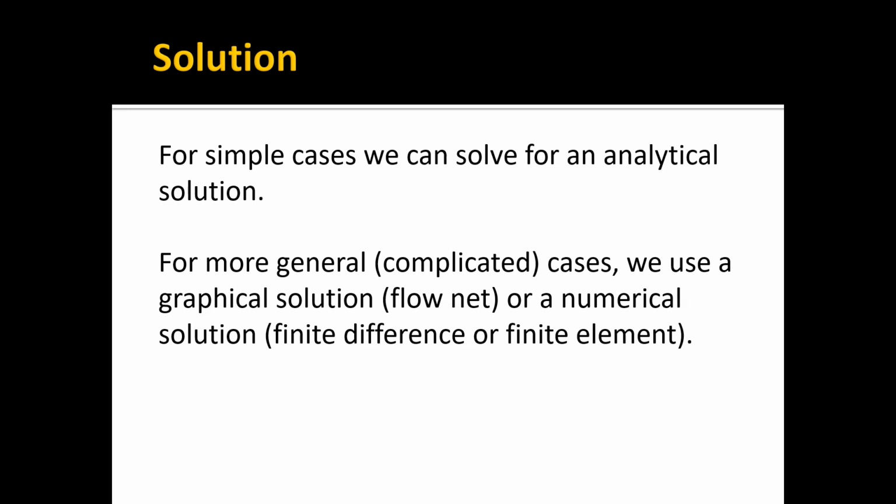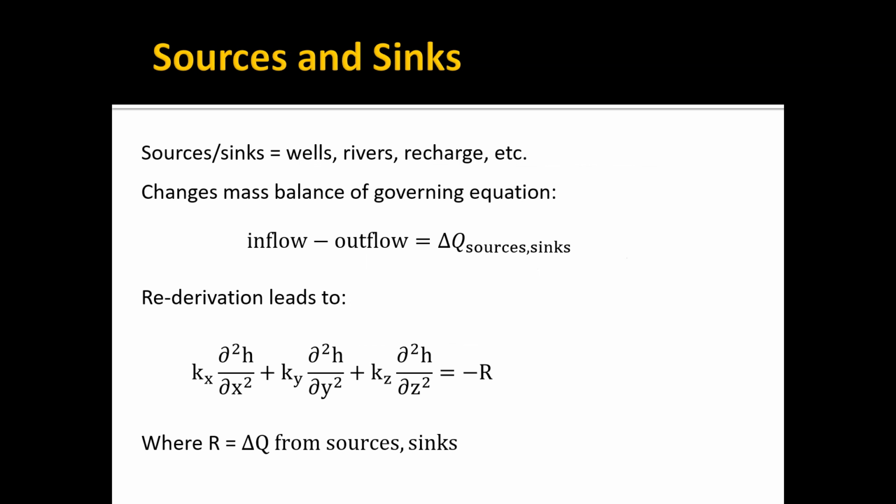It is possible to build a numerical model where you don't provide sufficient boundary conditions and it blows up. So we're going to discuss boundary conditions in pretty good detail, and we're going to talk about the different solvers that are used in MODFLOW. There are different algorithms for solving these equations that you kind of need to know something about in order to use it. So let's go back.